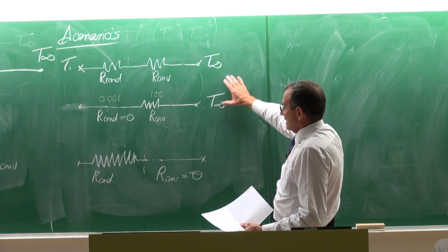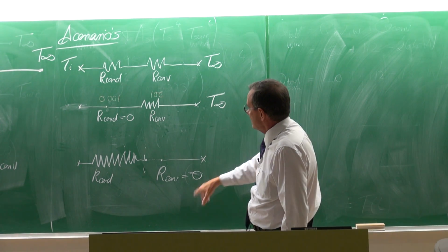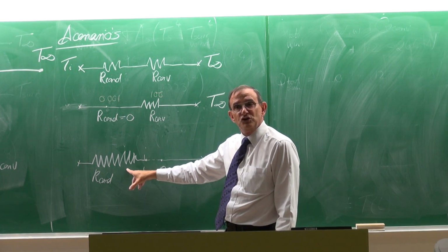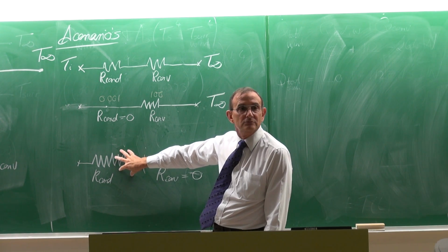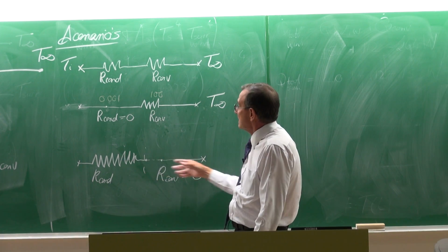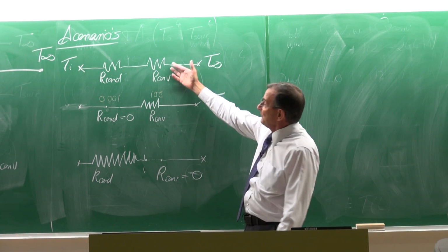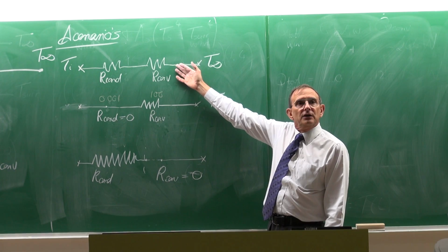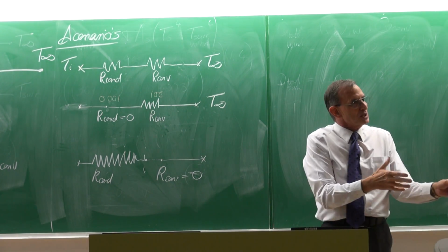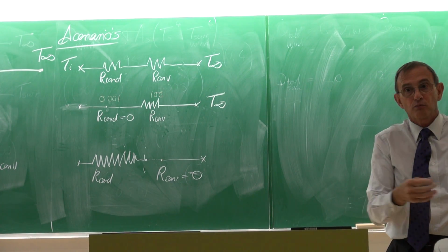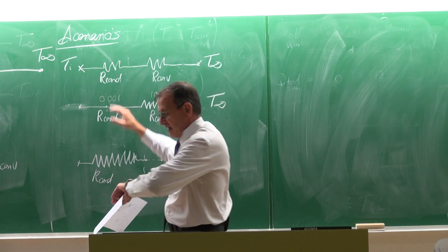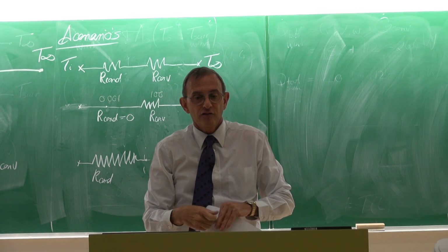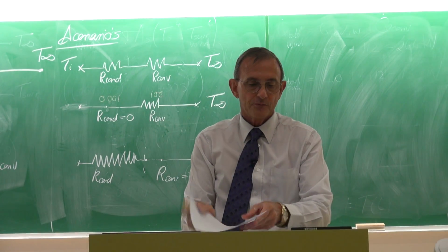So that would be in this case. In that case, you will see, for example, I have to concentrate on the resistance of the body if I want to increase the heat transfer rate. And in this case, it would make sense to give attention to both terms, because both of them have a significant influence on the heat transfer rate.